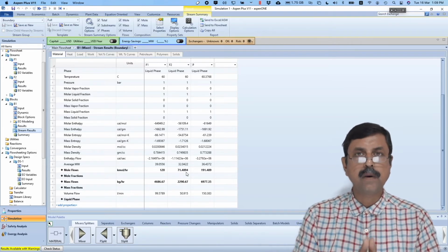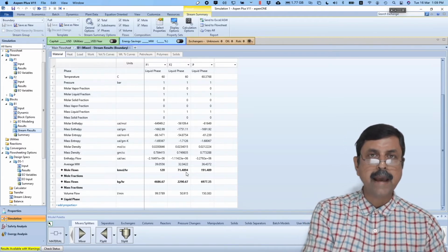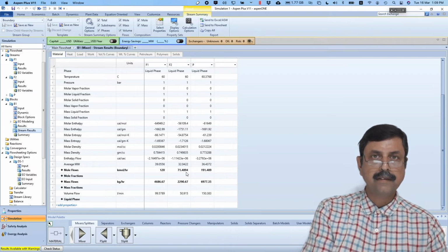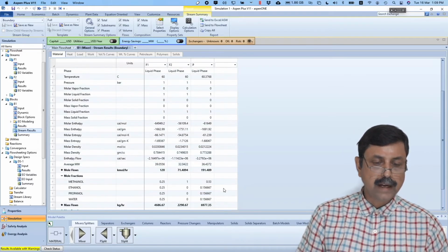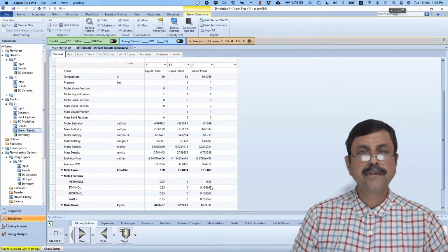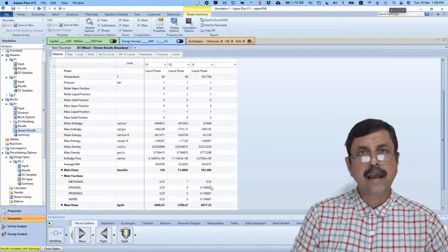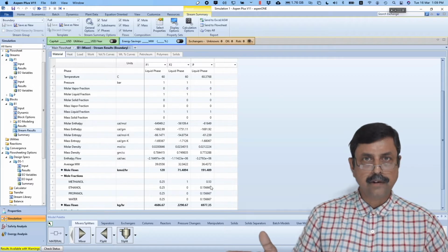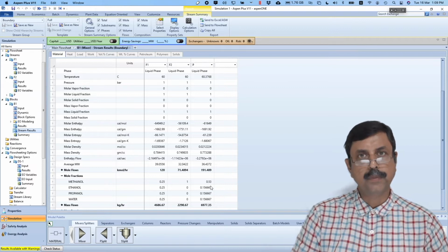as if the simulation wants you to design this specification as per your requirement and put it back to the actual simulation. Okay, so that's how the design goes. And once that happens, then mole fraction you will find 0.53 of methanol. So this is called sensitivity analysis and design spec, which go hand in hand. Sensitivity analysis will give you the range and design spec will pinpoint the value.